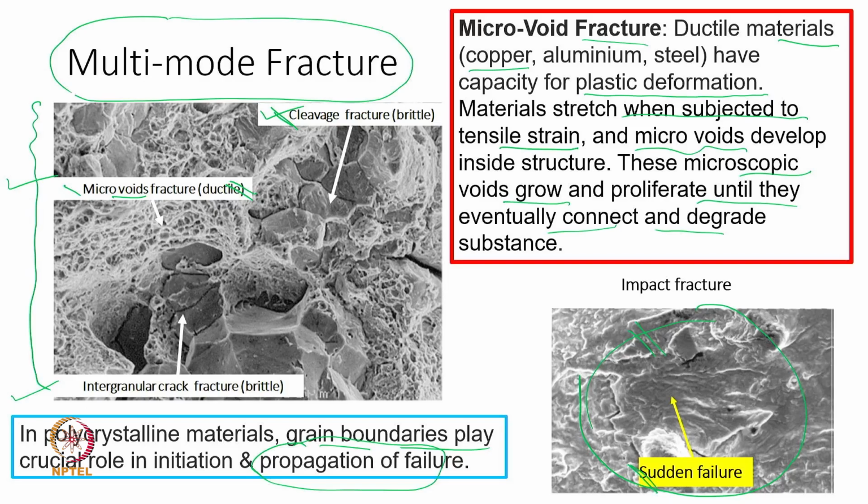It is really penetrating the grains themselves. It is not looking only at the weak side; even the strong side is getting damaged because of the very high loads. So, if I write from a load point of view, I say the micro voids will have a minimum load. Even the minimum load, because of the fatigue loading, will cause some sort of micro void. It may not lead to the final failure, but there will be some void formation, kind of slight porosity in the material.